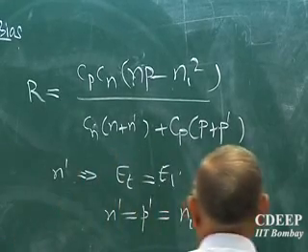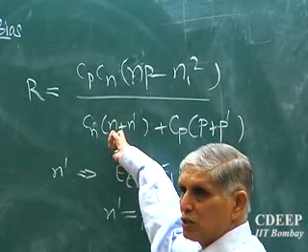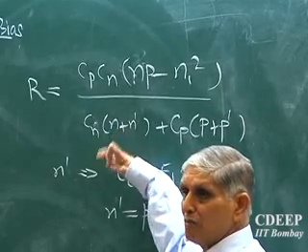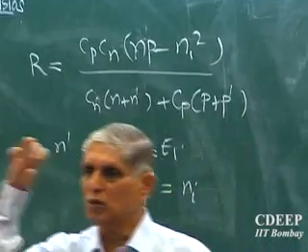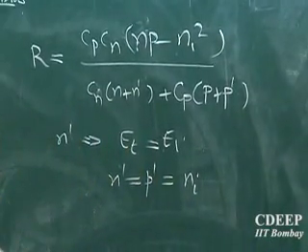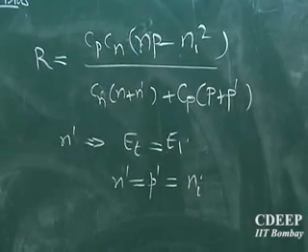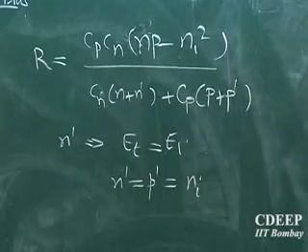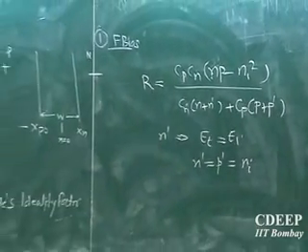Now if we make that assumption, then we write n related to EF minus Ei on the N side and Ei minus EF on the P side. What is the difference between the two Fermi levels? The applied bias, the e to the power QVa term appeared. That difference between the two Fermi level splits is essentially the forward bias. Where will the Fermi level be on the N side, higher or lower than P?